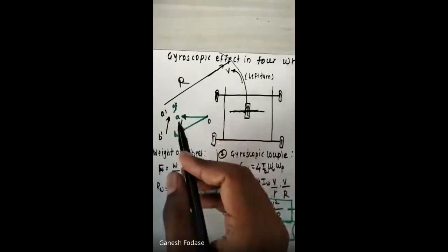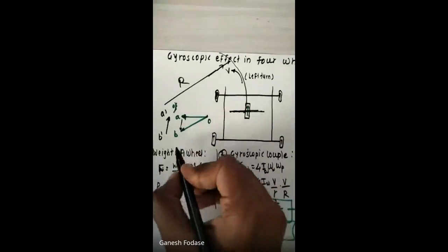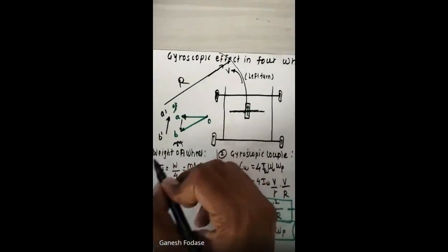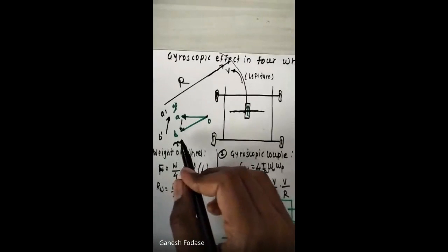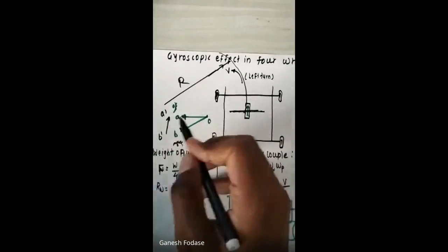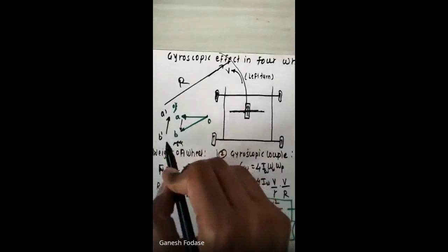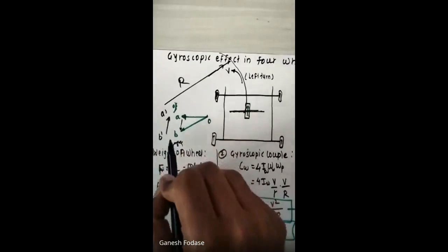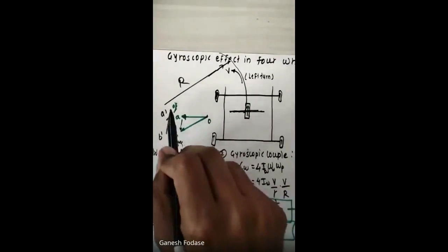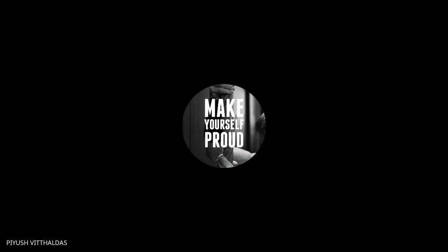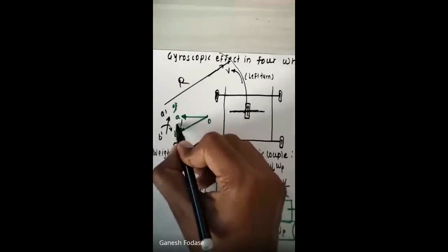And I told you how to observe the direction of rotation. If it is steering or pitching, observe from the right hand side of this. So this is your observer. Observer is here. What is your gyroscopic couple direction? You see this B dash A dash. Reactive couple vector is moving away from you. Away from you means clockwise, and towards you means anti-clockwise.